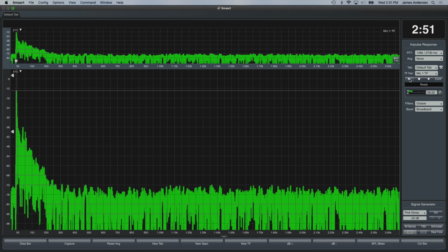But now the thing is, if I was doing a transfer function measurement, being able to tell the difference between signal and noise at 70 dB down is going to have virtually no impact on my measurement. That stuff is going to be a little micro squiggle in your transfer function line. It's not necessary. It's not going to have any impact. But when you're doing an impulse response measurement where we really want to maximize that dynamic range, get that last bit of decay out of that slope, that's where it's beneficial.